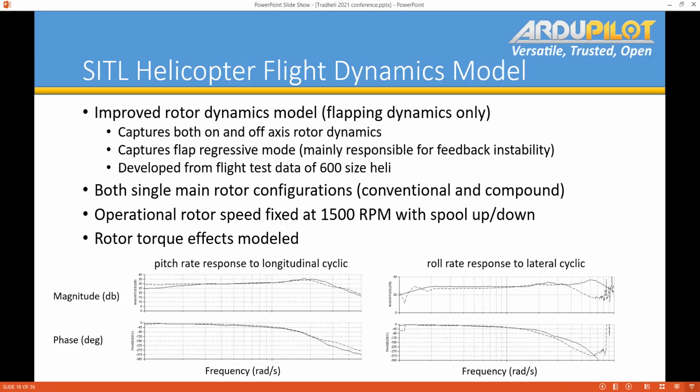Then you get the frequency responses, and you have to decouple those responses. There's a little bit more to it than what I'm saying here, but when I originally got this data, I actually wrote my own frequency SysID because I did it without having the feedback loops. The PID loops were all 0, and I did it that way.